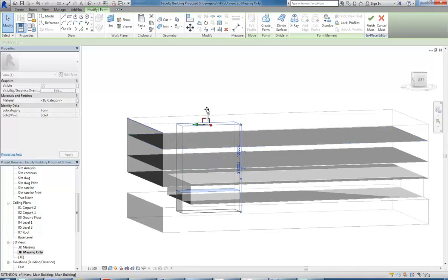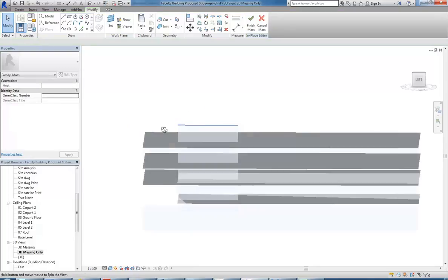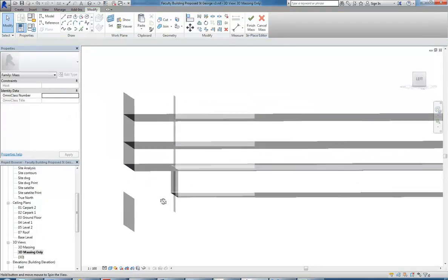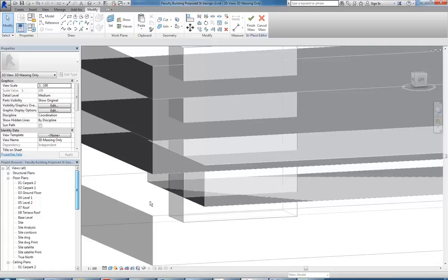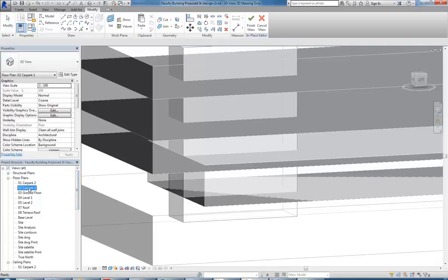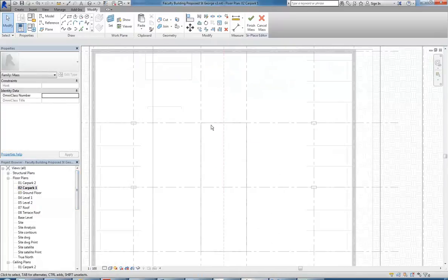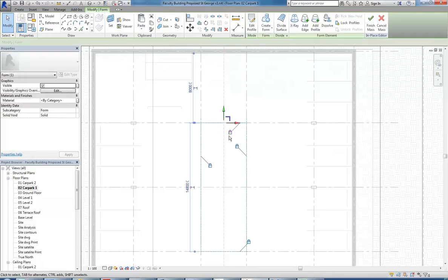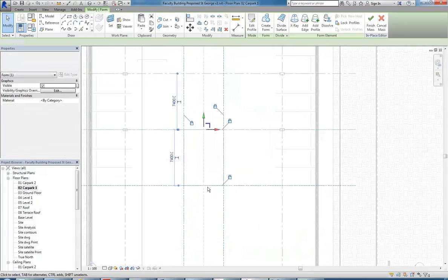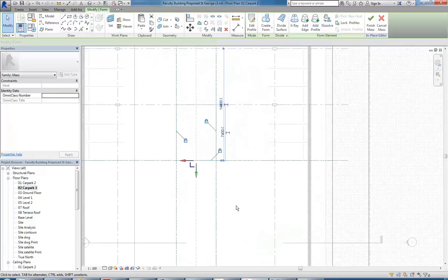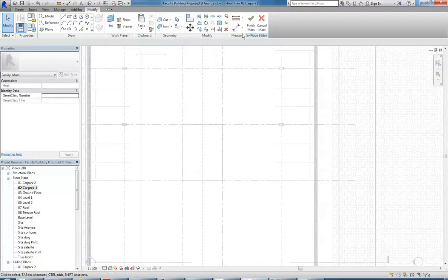So actually that goes through to the top. So that would be my core, and actually I can see straight away that I've done the ground floor setback on the same line, so right away I can say, well, that volume planning doesn't work. So if I go back to here now, to adjust that, same idea, I've got to make sure I'm getting the front surface, unlock it, and maybe I'll bring it back to here, lock it again, and then this might come back to wherever my next grid line goes, which I'll work out later.